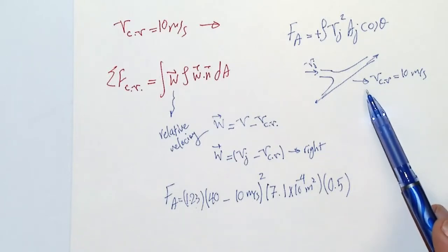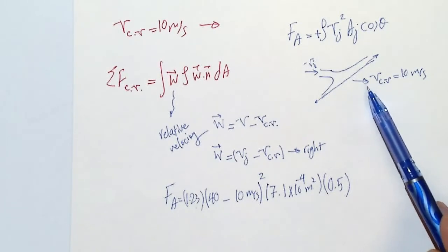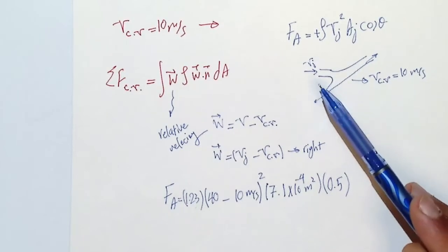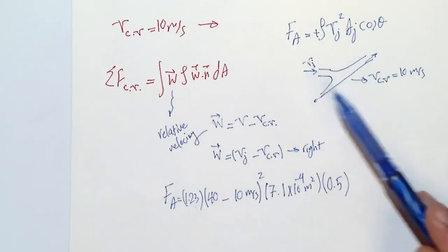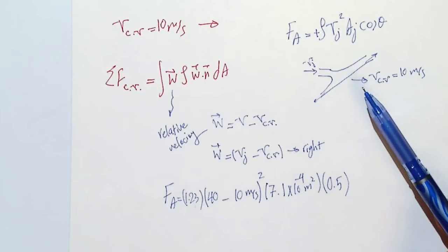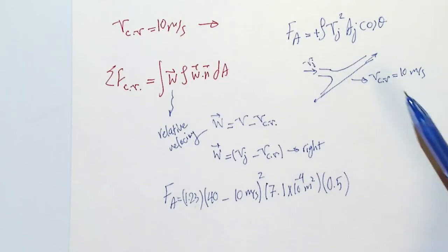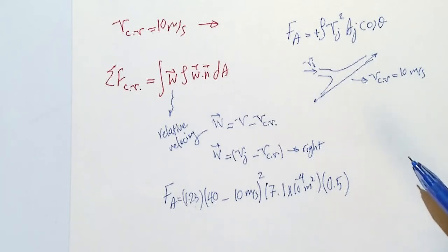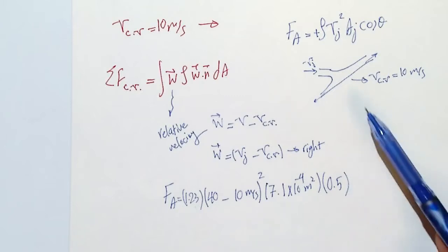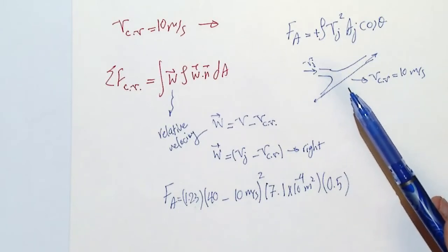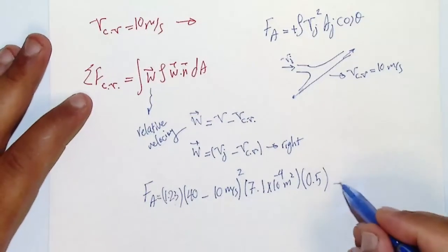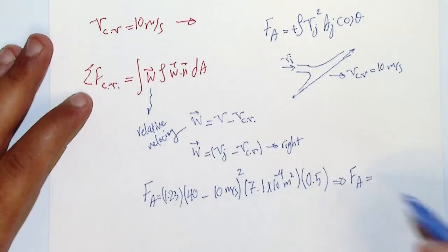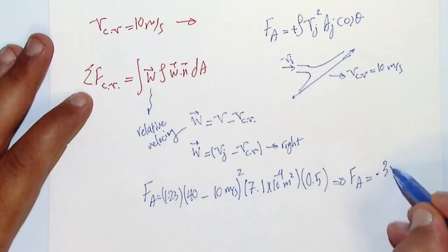And also if the control volume moves in the other direction, then you can assume that the plate is stationary, but the jet comes in and hits the plate at Vj plus V control volume, or 50 meter per second. So these are the different things that could be asked, but the only thing you need to change is the Vj, or the inputs in the direction, with the relative velocity. The answer for that also is 0.39 Newton.